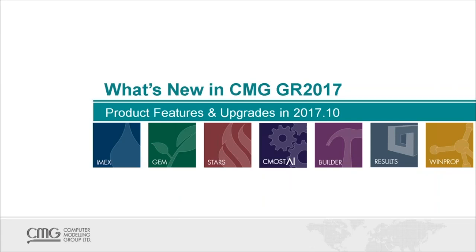STARS and GEM also have the ability to model reactions. So we talked about polymer degradation in GEM through reactions, and that can be modeled in both STARS and GEM as well. And also, if you wanted to set up a somewhat automated study where you're evaluating different types of polymer to see which one would be the best, you could define multiple polymers in STARS and GEM and just inject one at a time. Whereas in IMEX, you can only define one type of polymer.